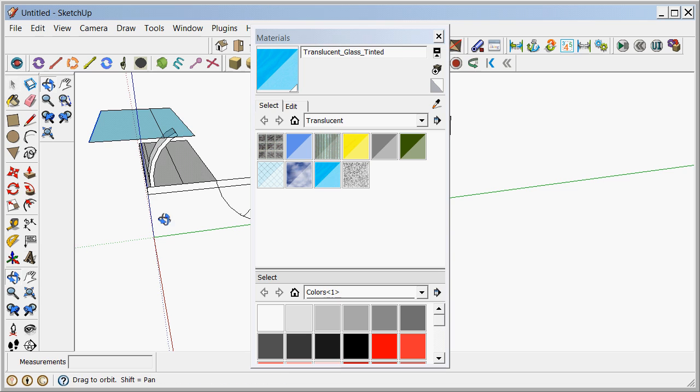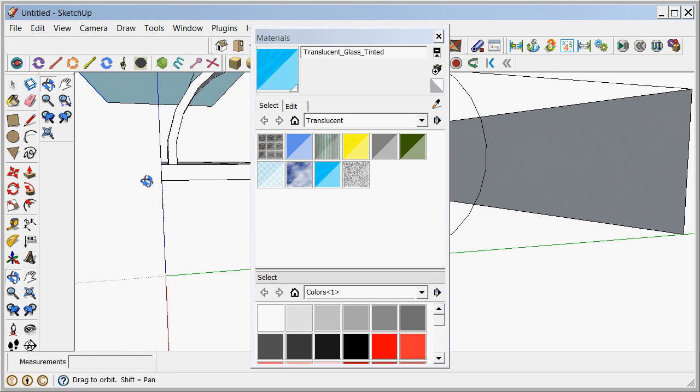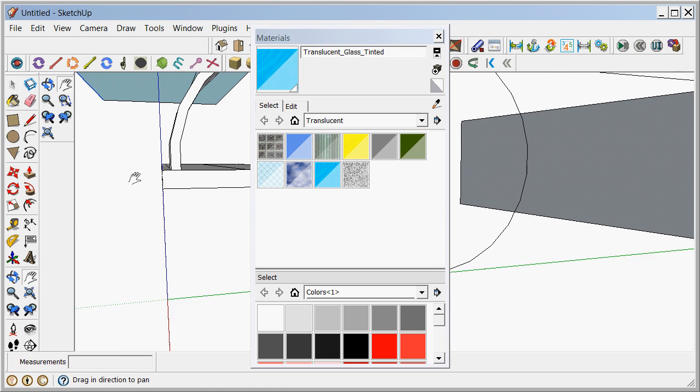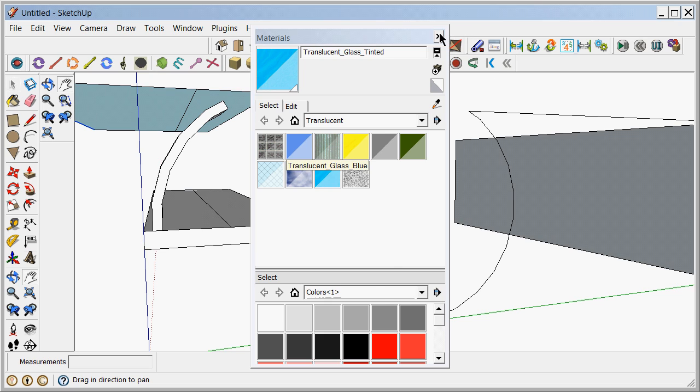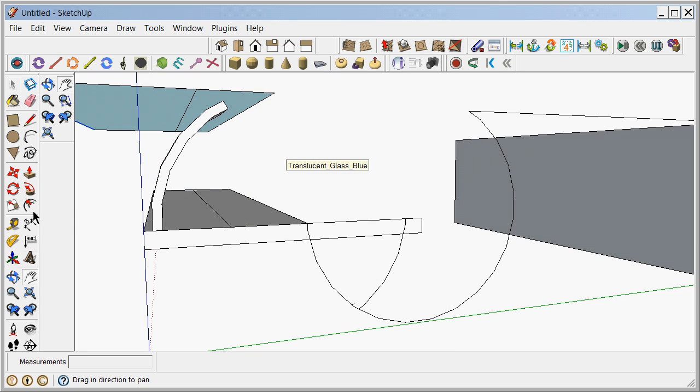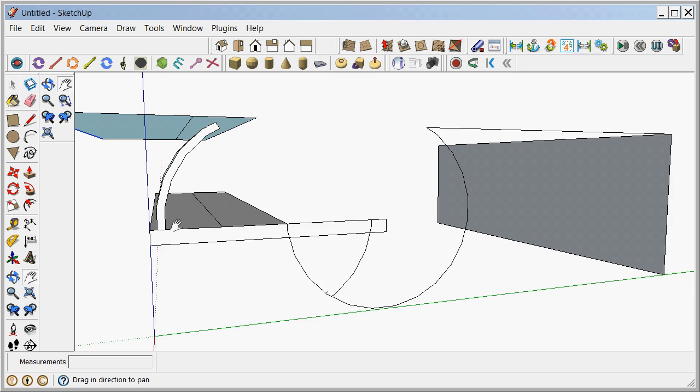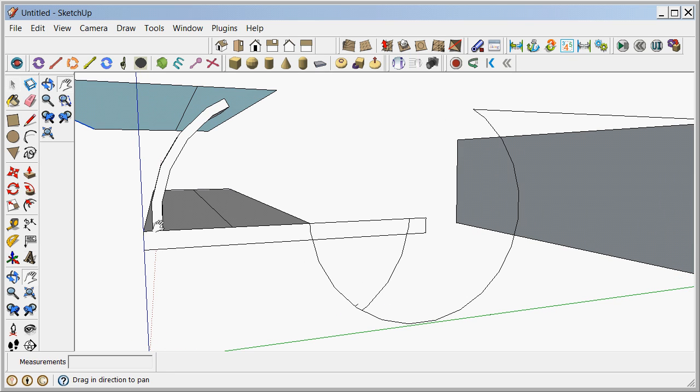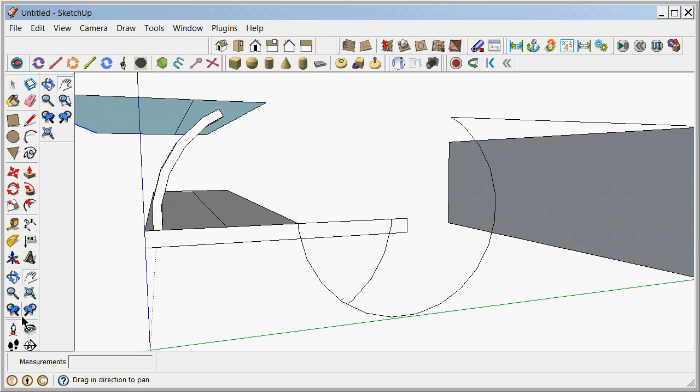Now, why the round gate? And what are we doing with the roundness? Well, mathematically, what you're doing when you're trying to calculate these is you're trying to break them up into pressure surfaces and weight surfaces that you can understand. So I'll do that next by doing a section through here. You'll see me push through.